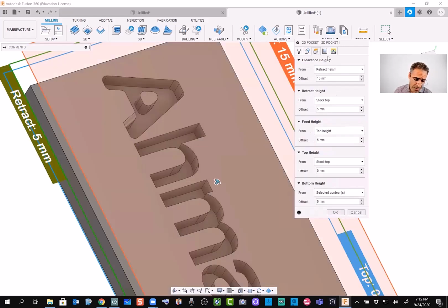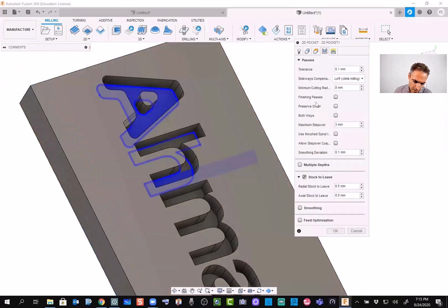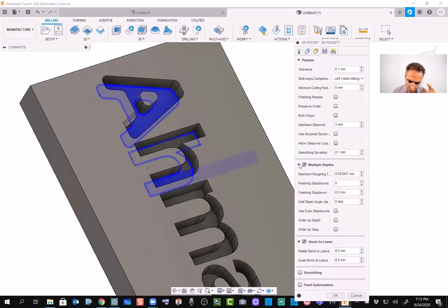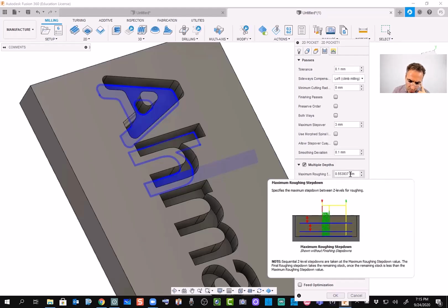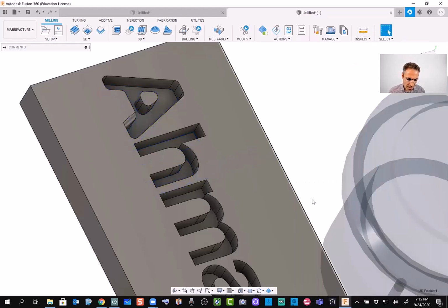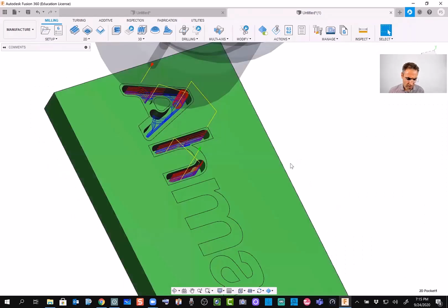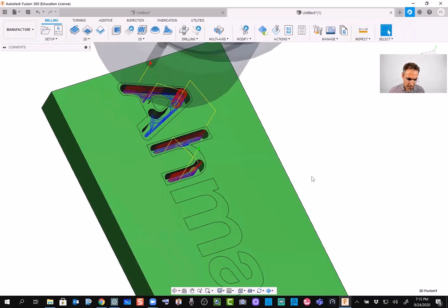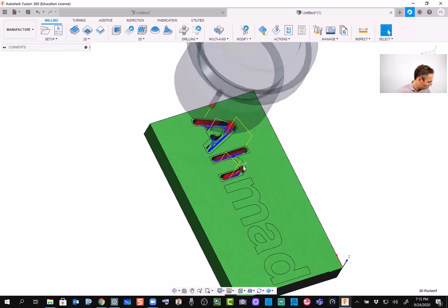Okay, what Ahmad you ask is the multiple step, right? This multiple step, this is the one here. So I select multiple steps rather than doing it one shot. Now this is where we can select. So instead of 0.5 millimeters, why not we do like 1 millimeter as a stepping down. And then we press OK. Okay. So let's see what happens. It gives us the toolpath.